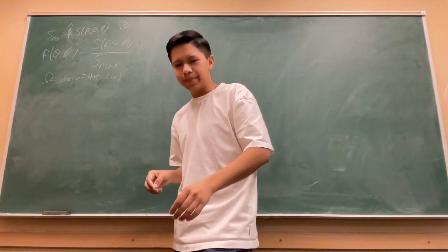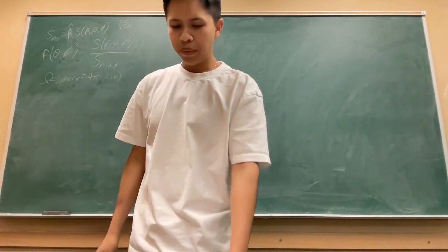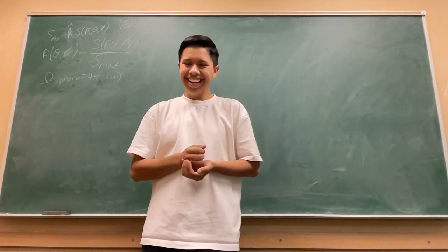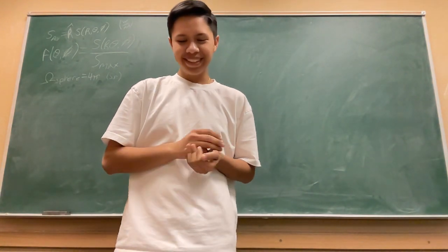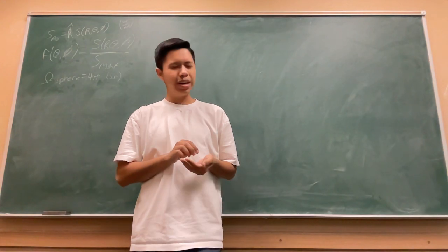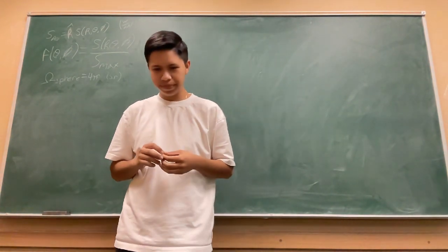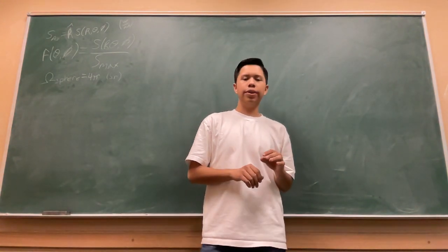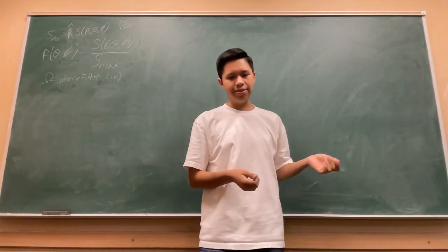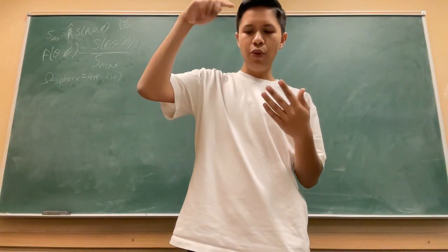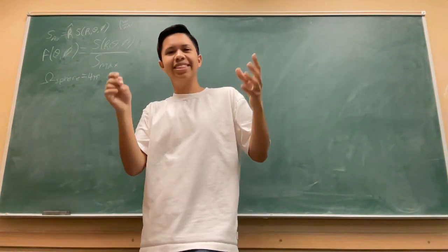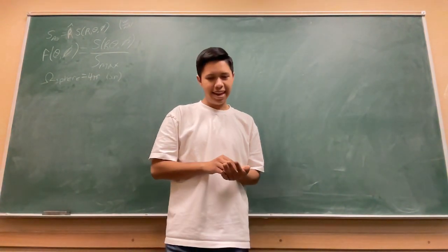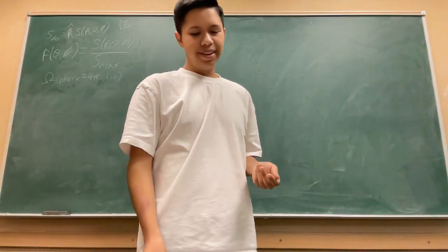Okay, so let's move on to 9.2. So what do we want to find? We want to find an antenna radiation pattern, or the radiation pattern of an antenna. The reason we want to find that is because we want to make a 3D plot of the strength or the power density of an antenna at a fixed distance from the antenna. We can also make a 2D plot, and this will be with a ranging theta value or a phi value, so just different angles of our antenna. We'll measure the strength of it in order to see how our antenna works in 3 dimensions, and we're also going to characterize that with a pattern solid angle, but that's later on.